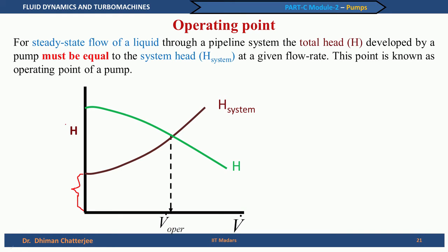And you may also ask, why does the pump curve start here? Because you remember the first term in the expression that we had got in the ideal case was A plus or minus B V dot. This A refers to the head developed in the absence of volume flow rate. You can imagine this way, that you have filled the pump with water, you close the delivery valve completely and you start the pump.